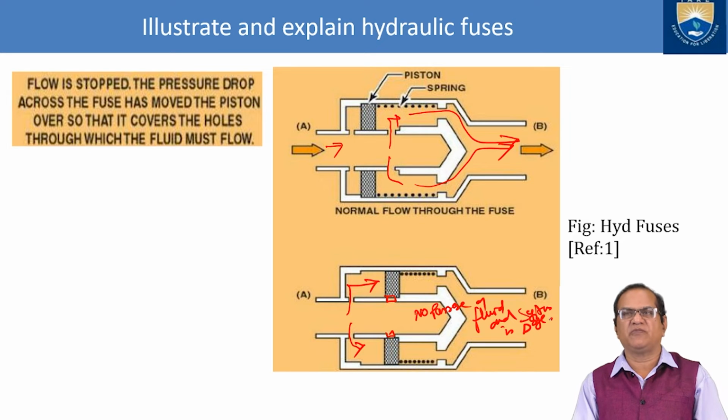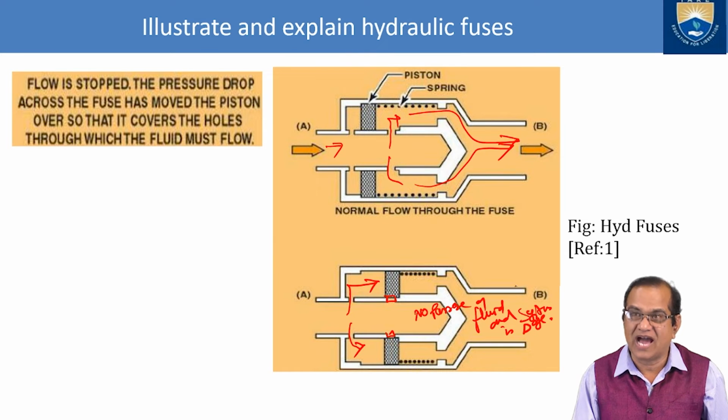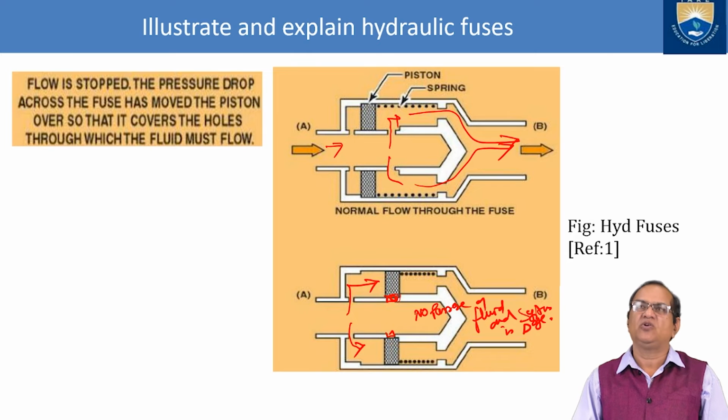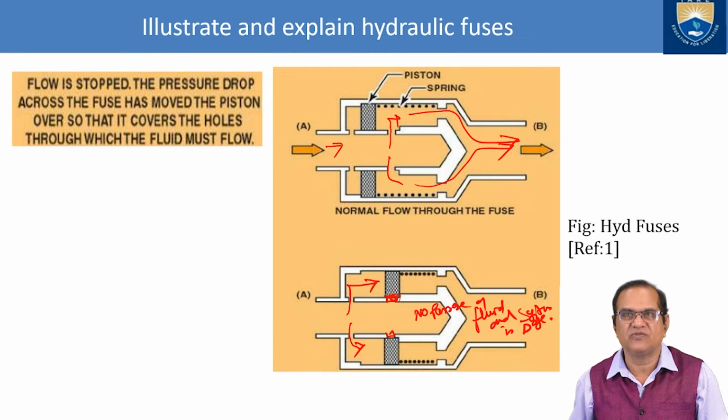So that is the purpose of the fuse here. Normal flow goes through the fuse, and here it is an emergency, or the high pressure is here. It will operate this valve and close this passage, and the system will be safe. So that is the purpose of the hydraulic fuse. It is acting like an electrical fuse.